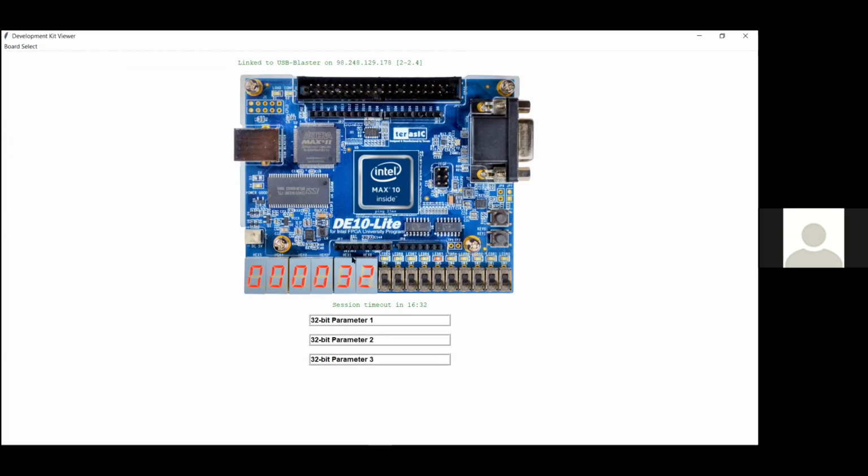So you'll see that this LED is scanning erratically left to right. It's too fast for us to perceive. So I'm going to slow down the speed that it scans at with another feature that we have called a parameter, which is a 32-bit adjustable register that I can click here, type in a hex value. It's a great way to teach number systems, etc. So I'm going to type in 19, hex 19 here. And we can see that we've divided down the speed of the scan slow enough so hopefully you can see it over the web.